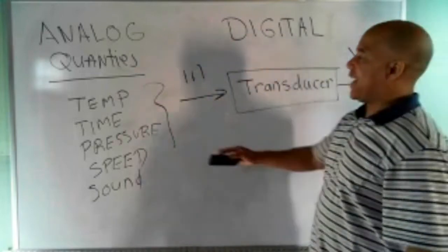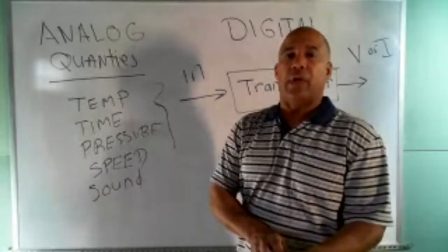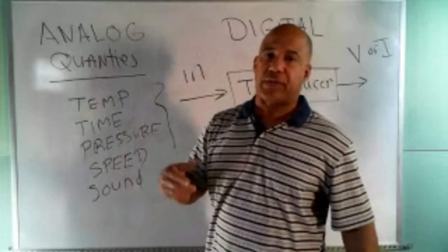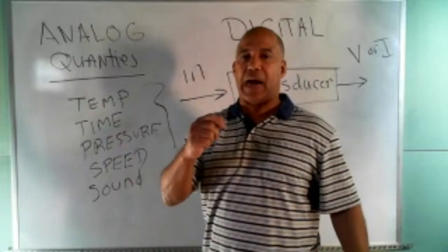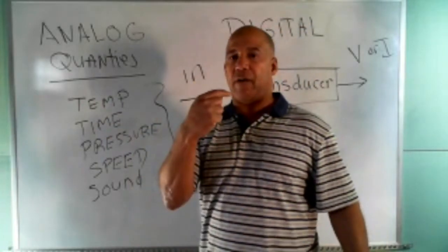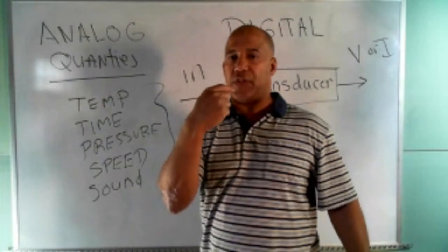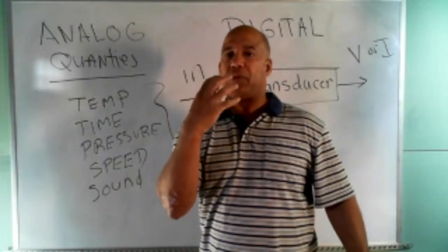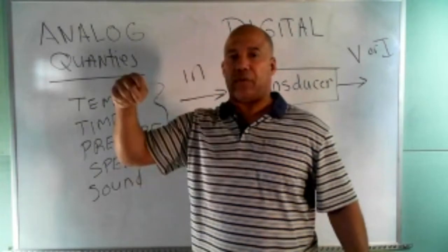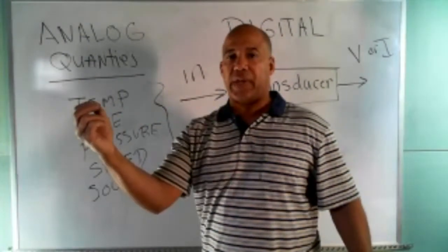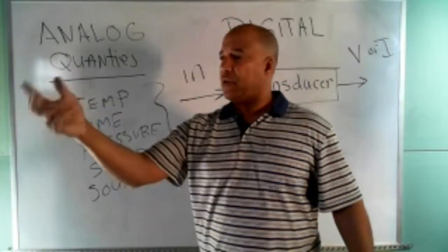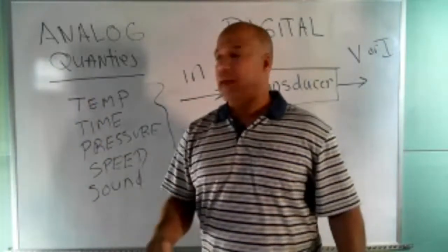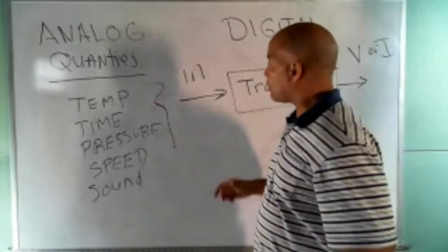So I can take a temperature. You probably have a thermometer with this virus thing going on. You have an electric thermometer. The thing you put in your mouth is a thermal resistor or some kind of thermocouple. It takes the temperature of your body and changes it to an electrical signal. And there's a little chip, a little circuitry inside that changes that to a digital display, an output that you can read. It's a transducer.